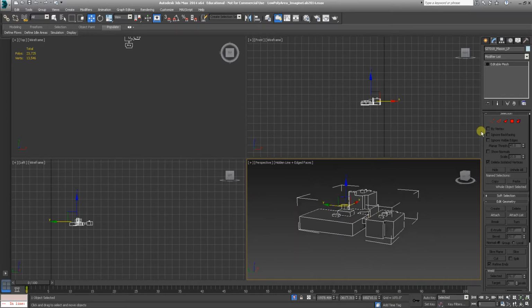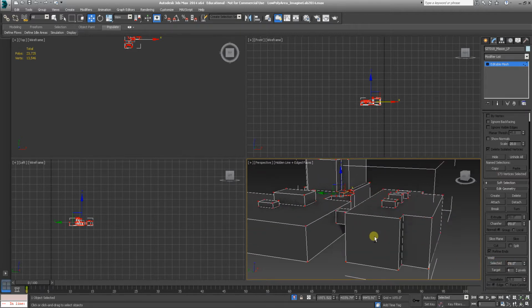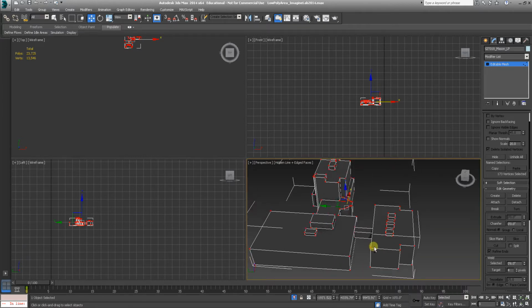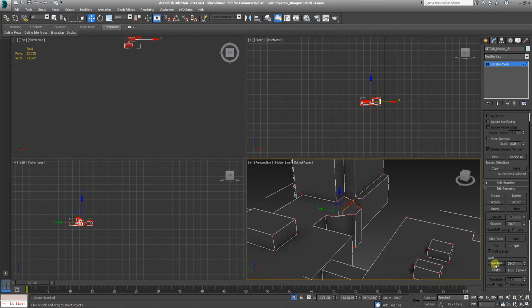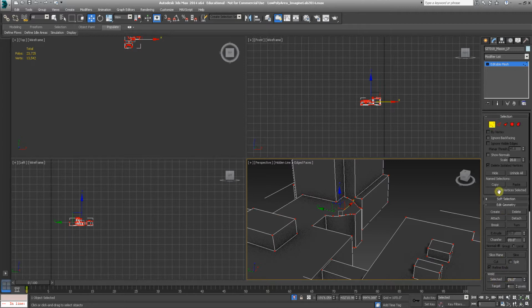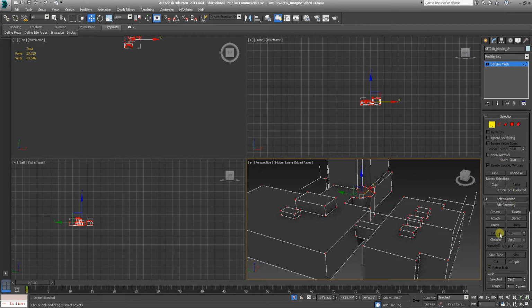So now it's attached. What we need to do now is go into the Vertex Mode and select all the vertices. Control-A will do that. And weld them. I've got a 6-inch threshold because I'm at 1 unit equals 1 foot. A lot of our details aren't at that smaller resolution, under a foot, to cause any issues. You can see that pivot point jumped when I weld it. And you can also, and I'm undoing this real quick, there's 169 vertices, there was 173, so that number seems about right to add 2 rings of 4 vertices and make sure they're connected.